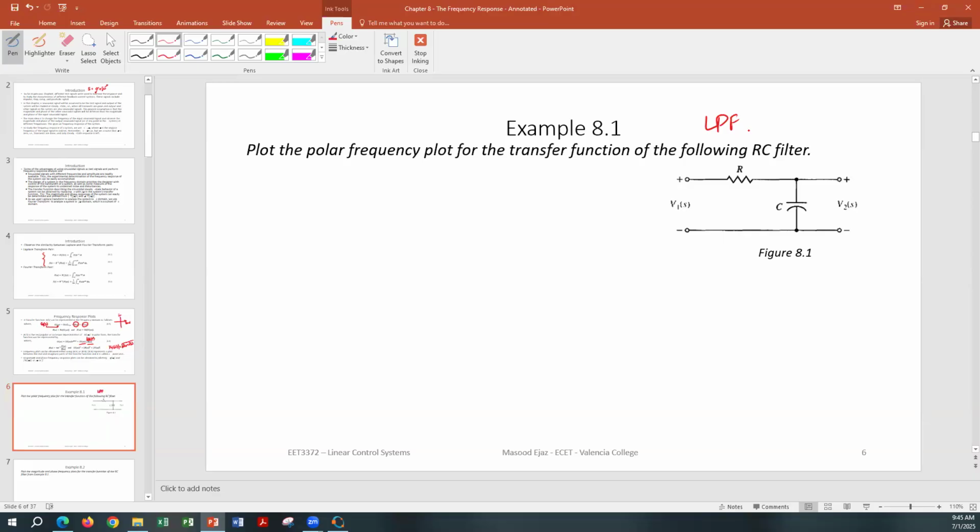The order of a filter or order of a circuit simply represents, when you write down the equation for voltage or current, the order of the differential equation. Or in other words, the number of reactive elements in the circuit represents the order of the filter. Because if you have two reactive components, RLC for example, which you discussed in circuit analysis, those circuits were second order systems. Because when you write down the voltage equation or current equation, it's going to be d squared over dt squared plus d.